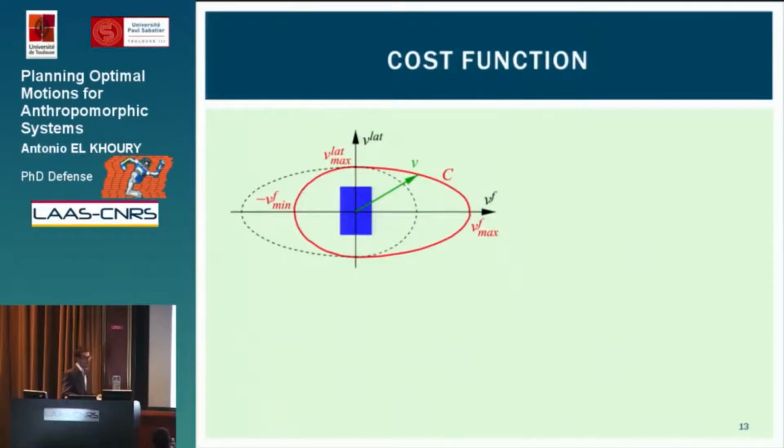What we want to do is make the robot go forward as much as we can. Experimentally, we have observed that the robot walks faster in frontal motion. So what we can do is define a constraint. It's a virtual constraint. It doesn't really exist, but it allows us to say that the forward speed is actually, here we have the bounding box, and that's the tangent path, greater than the lateral speeds, as well as the backward speed.